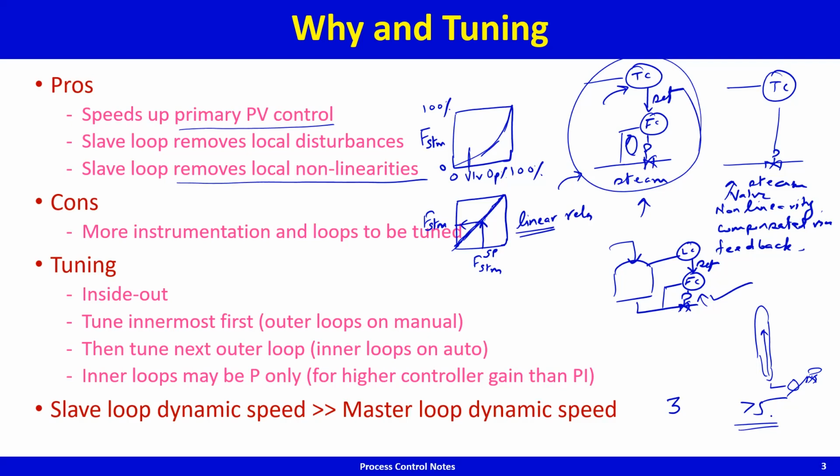On the other hand, let us say reflux is maintained in ratio with the distillate. In response to that, the distillate rate will change. So now there is this secondary effect. The reflux rate will change, and the flow over the trays will change. So you see, there is the primary effect, and then there is the slow reflux effect.